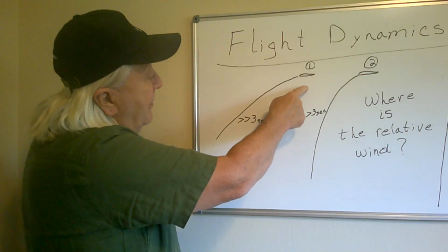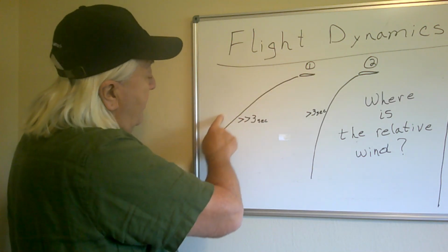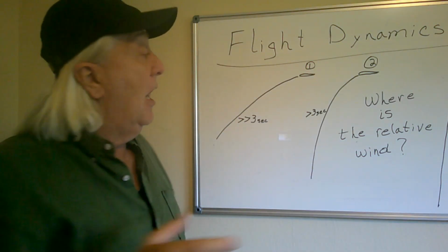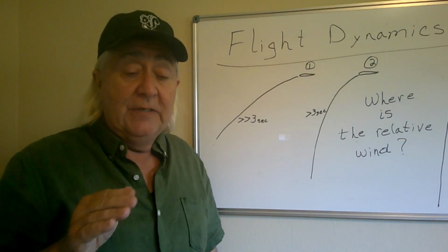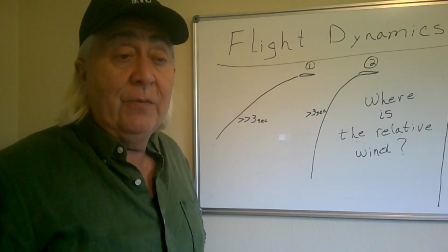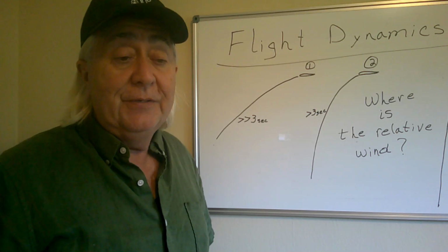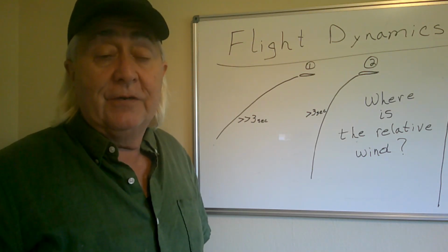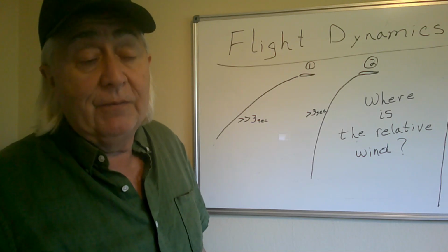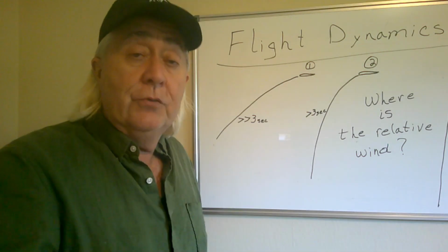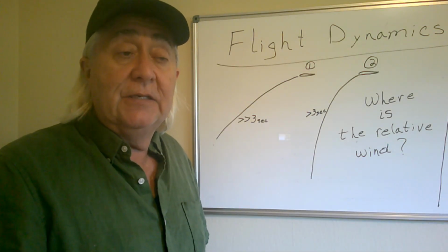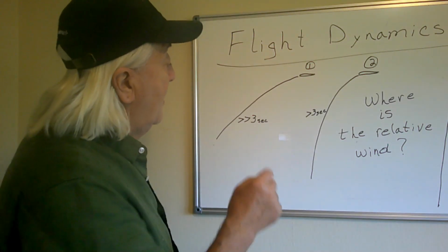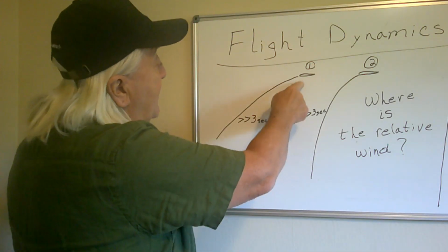Well, that's this kind of trajectory right here. It's an arcing trajectory that heads on down to the ground, and it takes time for that to happen. This is like an incremental thing. I don't think anybody would come in and just dump full flap and find out they don't have enough elevator command. Might have happened that way, but then there's another root cause to the accident, and it's not the fact that he ran out of elevator command. So he'd be on this type of trajectory.